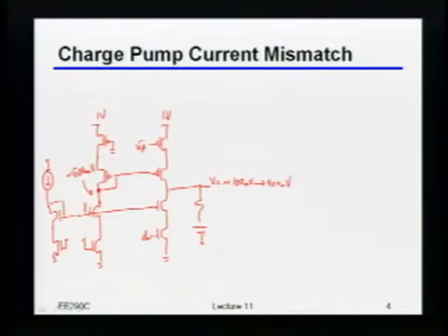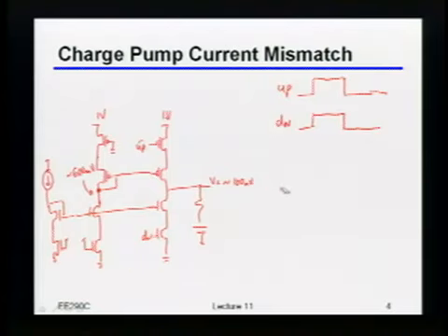So now this actually creates an interesting situation. Remember, we're using this thing to act like a transconductance stage, right? So let's think about what happens if I take an up and a down signal that are totally lined up. Because remember, for my PFD, there's always going to be some finite width pulse that I use just so that I avoid the deadband problem, right? And let me just move this over so I've got some space. Let's say 100 millivolts and 900 millivolts.